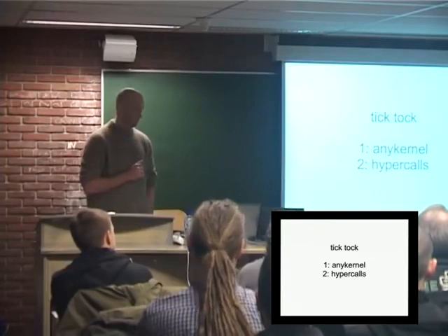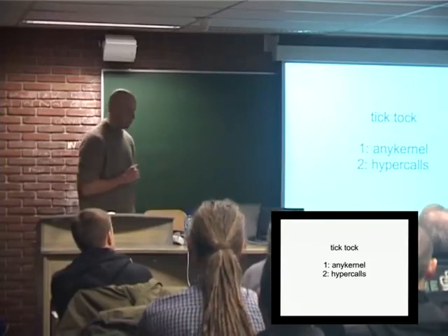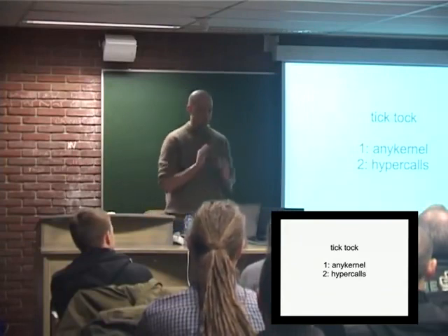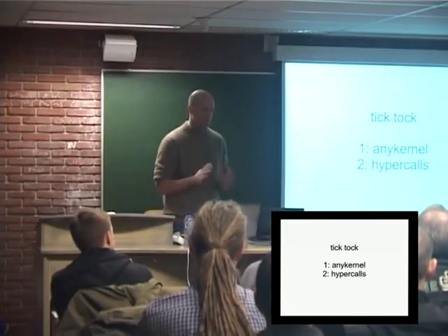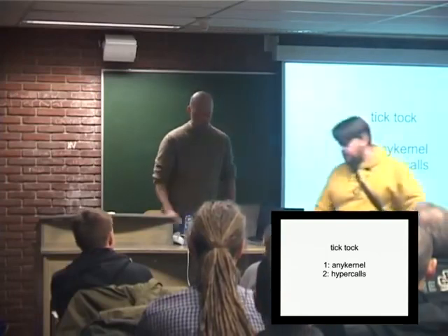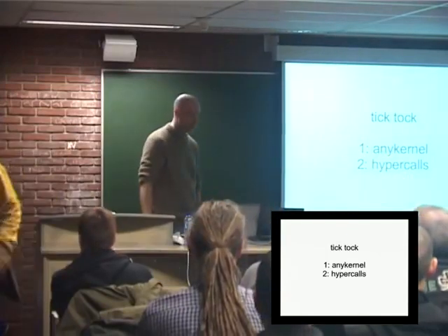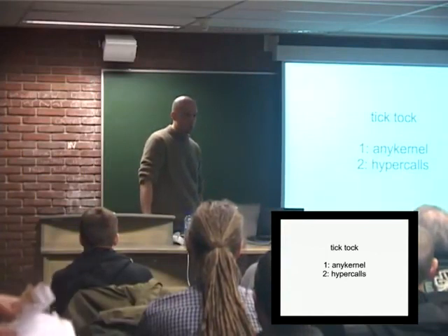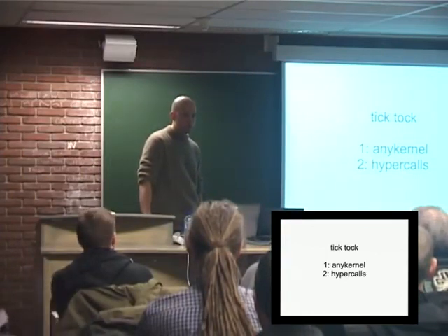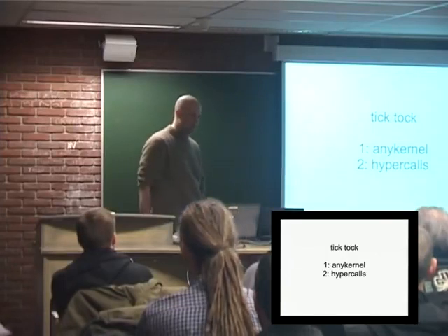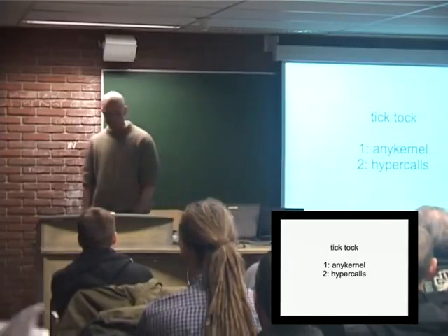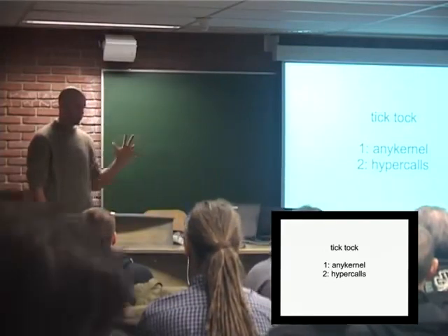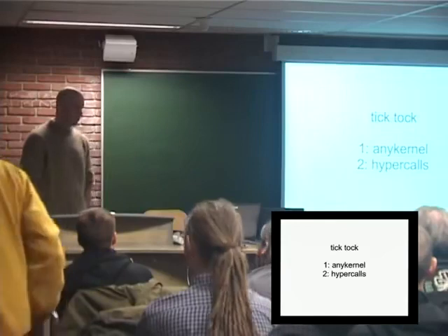But guess what? It's actually quite easy. But there's a small number of certain kinds of changes you need to make sure that the drivers really are orthogonal to all the other components in the system. And this can be done without any linker tricks, indirections, or anything like that. So I just use the normal linker, and I'm able to select the set of drivers I want.